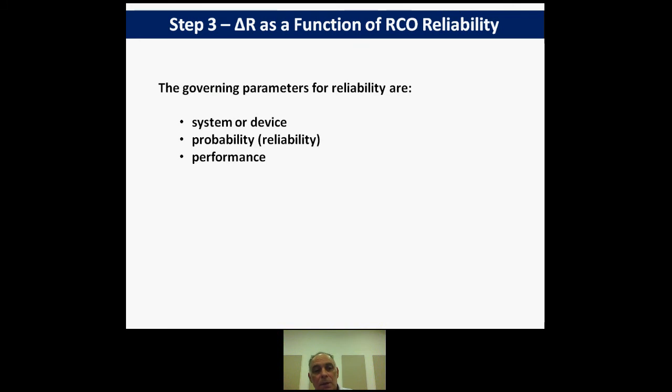what we're looking at. We know there are some mechanical devices like pumps which might not operate at their full performance, but they might be able to operate at 50%. Is that okay for providing some sort of risk reduction, or is it not acceptable? We either want full performance, or we can compromise with some partial performance. This is very important. For what period of time? Because nothing can be reliable forever, so we have to specify time.